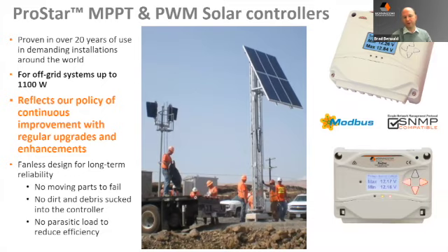And most importantly, this product offers built-in load control. So when we're talking about an industrial application where it's unattended and there's a DC load and it needs to be managed remotely and in an automated way, the load control is offered on all these products. And that's important because when we look at some of the data discussions today, you're going to see that knowing what is coming into the system from the PV array and also what's going out is really critical, because if you don't have that data together, you're not going to be able to see that you have the right balance on the array for the battery, that you're not going to see what your load is actually consuming.